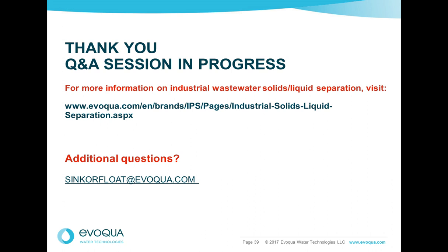We'll look at modifying scum and float handling processes to handle short term upsets. And it depends on the process, but sometimes if it is a short-term seasonal variation and carryover, we'll look at doing some post clarifier polishing, often with a DAF, particularly if it's solids that are unique to a process that results in short-term floating of solids within a clarifier. Using a DAF as a post-polishing step can sometimes be a real cost-effective way of addressing it.